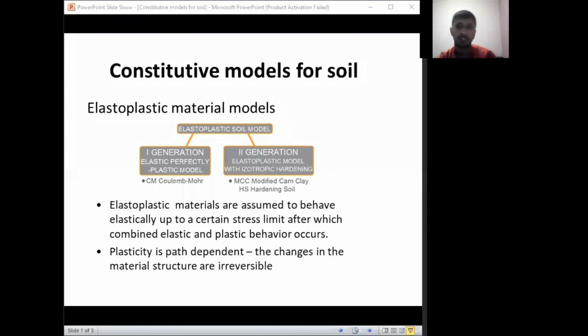Now let me talk about constitutive models for soil. Constitutive models are assigned to enable estimation of behavior and prediction of actual complex soil reaction to applied load. Failure theories describing constitutive models identify soil failure or yielding with a boundary surface, dividing the principal stress space into linear elastic and plastic material behavior. Ideally, a perfect soil model will be able to predict soil behavior under all types of loading conditions. An increasing number of stress relations have been formulated to model the behavior of soil.